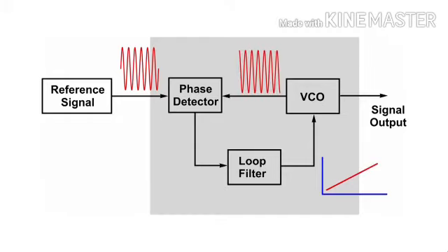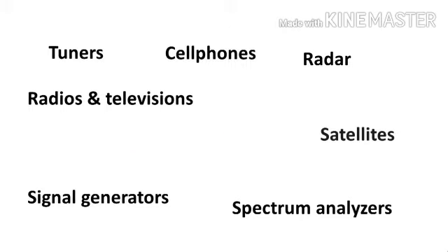As there is a fixed phase difference between the two signals, it means that the frequency of the reference and the VCO are exactly the same. The loop is locked. So what's the use of producing a signal on exactly the same frequency as one you already have? If you look at it simply like that, none at all. But if you use the phase-locked loop in a more imaginative way, it can be used for many useful applications, from FM demodulators to synthesizers and much, much more.